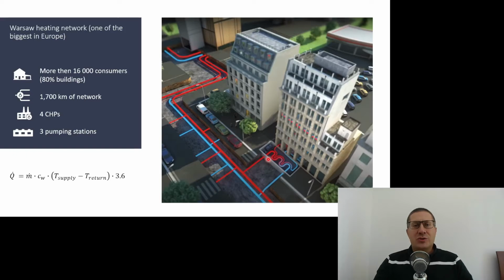So we need to be sure that by doing this, we have enough pressure difference, so we really can push the water through the network. We are not exceeding the flow limits in the network, in the chambers, in the substations. Then this solution should be optimal.